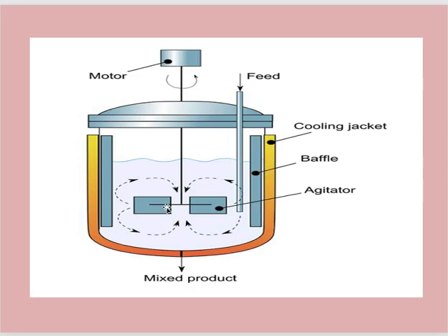So we discussed the agitation. We considered agitation one of the most important. Here is the motor, variable speed or fixed speed. This is a very important point, and I want to make it clear here: when you make an interlock system to protect the reaction rate or protect the equipment, you consider a standby source of electricity for this motor, because if you lose the electricity from source number A, you can use number B, cut in immediately, so as not to stop the reaction inside this reactor, okay? Here, baffle inside, coolant jacket, feed in like this.